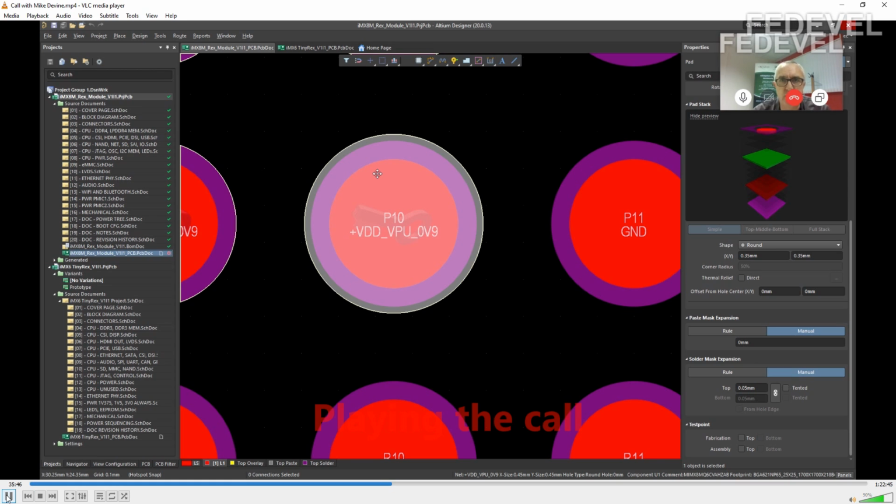Okay. And then those holes, we drill those only on the panel. We then plate the barrel of the hole, and then we'll either resin fill them or copper fill them. And what we do, we create a mask to just expose those holes which need to be either resin filled or copper filled. So then we would run that process of filling them. The process after that is we do need to have a planarization, because we've got to take the surface copper back down, otherwise you'll end up with bumps where the holes are. We then drill the remaining plated through holes and go through the process again.